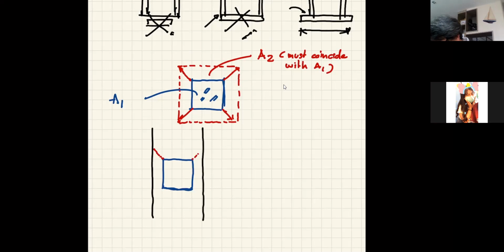Likewise here, if I draw everything at 45 degrees, that becomes the area of the concrete that I can have to resist the load coming in from the steel plate. This is limited by the natural barrier of concrete.